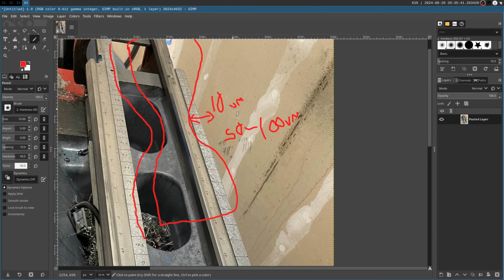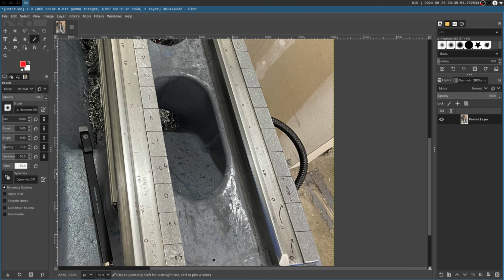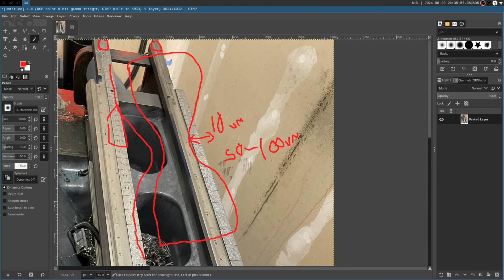This is the foundation. This is what everything on the lathe sits on. This is where the moving carriage sits. This is also where the headstock sits, which holds the part. So this is literally the reference surface. Now, in reality, the bearing points of the headstock are these 4 corners. So from the factory, they actually didn't care about the finish of the rails behind this line. They effectively just worried about these 4 contact points with the headstock.